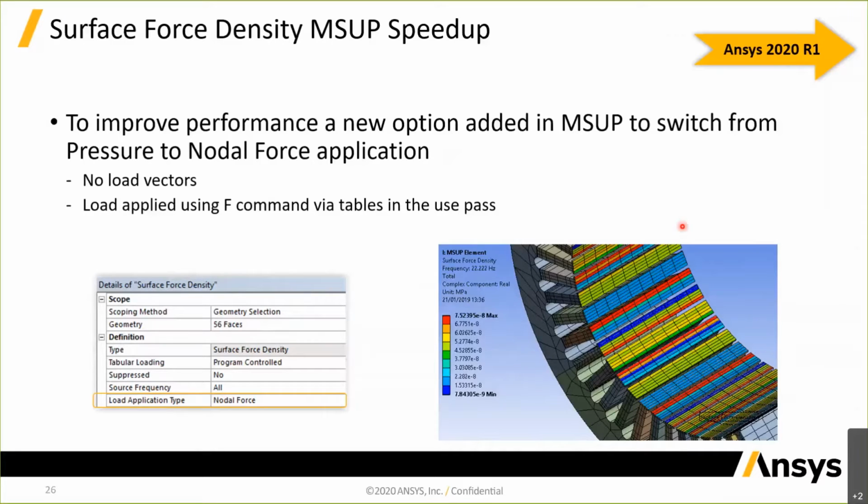And so once you get up to the latest versions of 2020 R1, and then soon to be 2020 R2, all of these waterfall diagrams, whether you're using the object-based force transfer, which is really good for most electric machines with a lot of teeth like it has here, or if you're looking at the element-based force mapping, which might show up in some more complicated 3D models, maybe with skew or maybe with something that's not as regular, then it's going to solve very efficiently, because we need to solve a lot of points for frequencies and speeds, but the efficiencies here in the new versions make that very accessible.